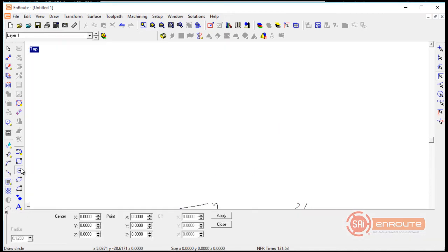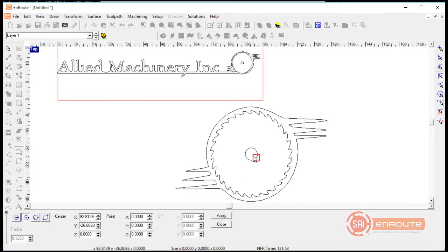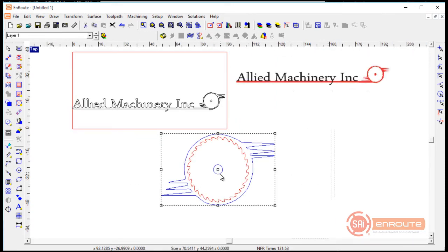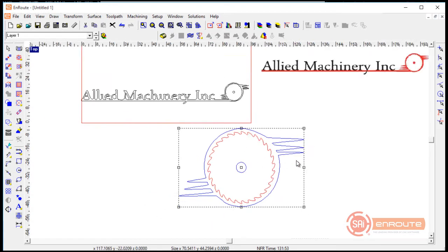And if I wanted to, I could come over here and just draw a little circle. Let's turn off this snap. Just kind of approximate it in the middle here. All right, that looks pretty round. Just want to make sure that I've got a pretty much round shape here. So that will suffice as my logo there.